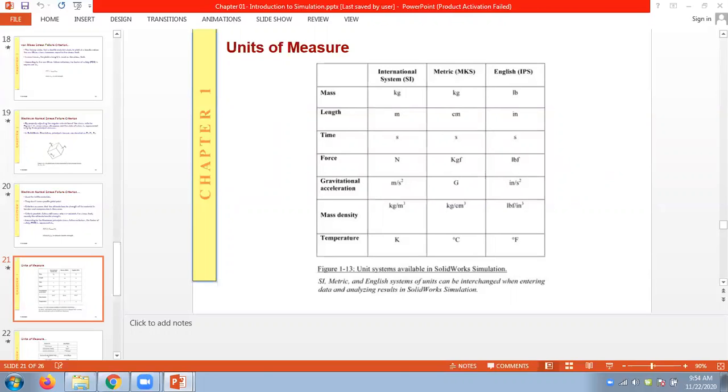But if you are doing a simulation, you can actually reduce that factor of safety. So that's why we are doing simulations and try to optimize our model without wasting materials unnecessarily. Instead of having 2-inch thickness, we can have 4-inch thickness and increase the factor of safety. But in mechanical engineering, the problem is we will increase the weight. So when you increase the weight, there will be problems of fuel consumption and other problems will come. So in mechanical engineering, we don't have that luxury of increasing the factor of safety as you wish.